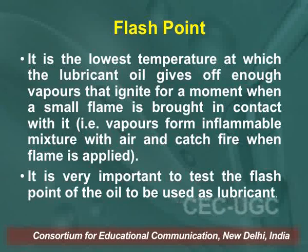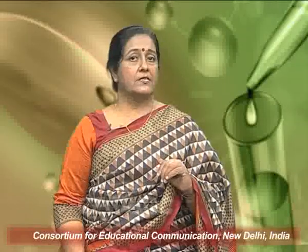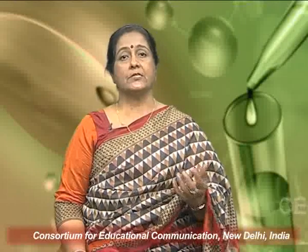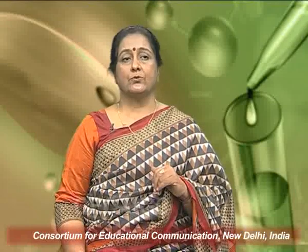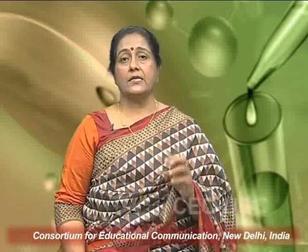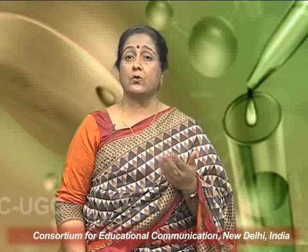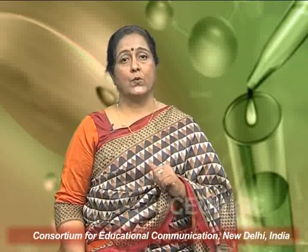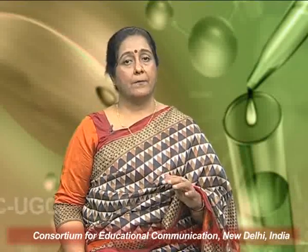It is very important to test the flash point of the oil to be used as lubricant. It is not advisable to use an oil as lubricant which flashes or reaches combustion temperature under conditions of lubrication. This is due to the fact that spontaneous combustion of oil vapors occurs if the oxidation is so rapid that heat of oxidation is not dissipated quickly enough to avoid reaching the flash point or combustion temperature.